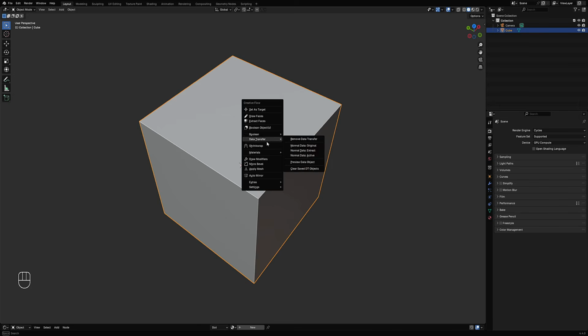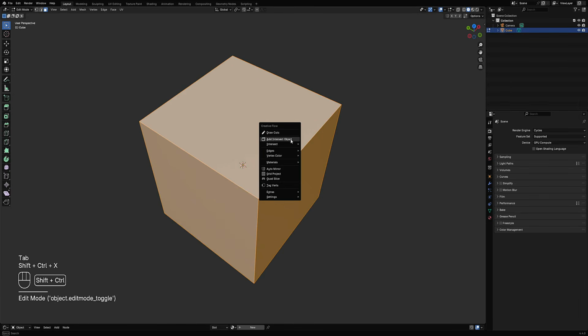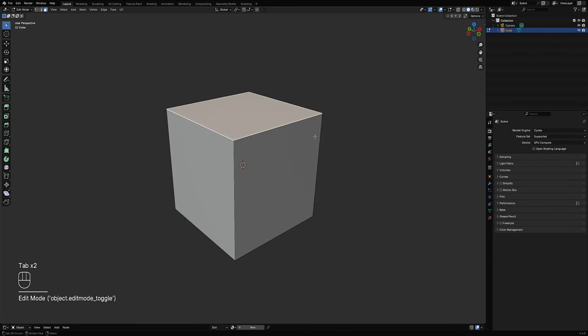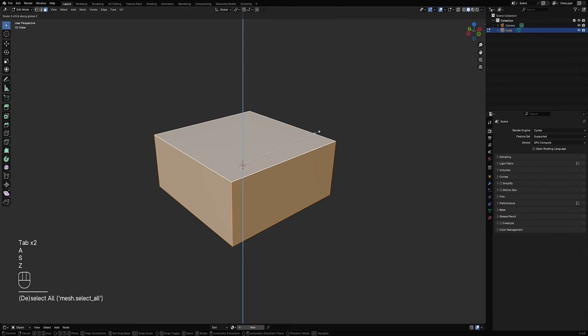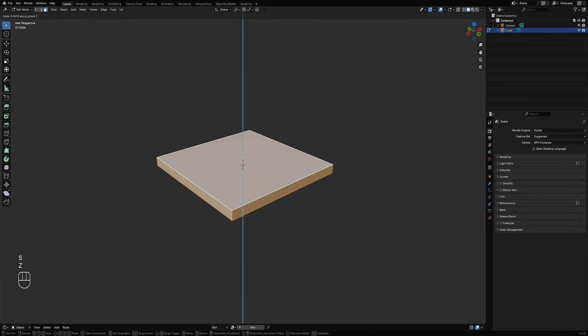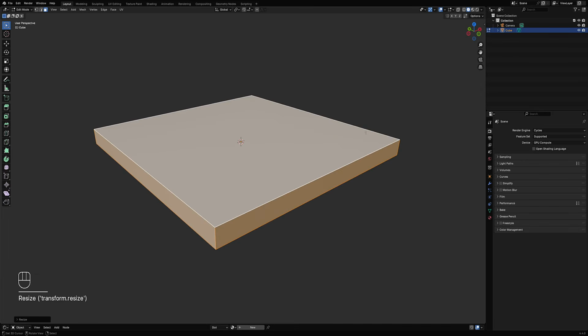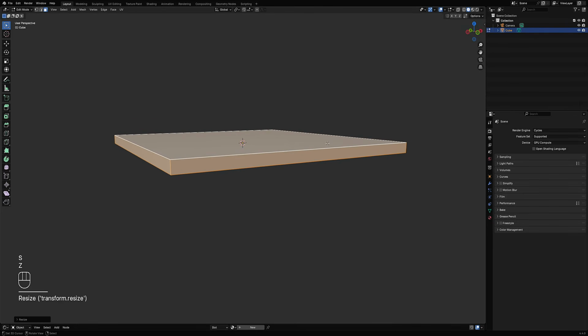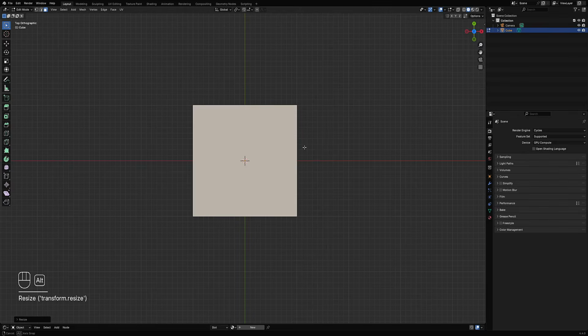There's also another way, which is the add intersect object, and it's also equally powerful, but that will be mostly for another video. Okay, so we're not going to use a plane for this because we're using Boolean, so we're just going to create something like a plane, but it has thickness to it, just to make sure that the Boolean works correctly most of the time.